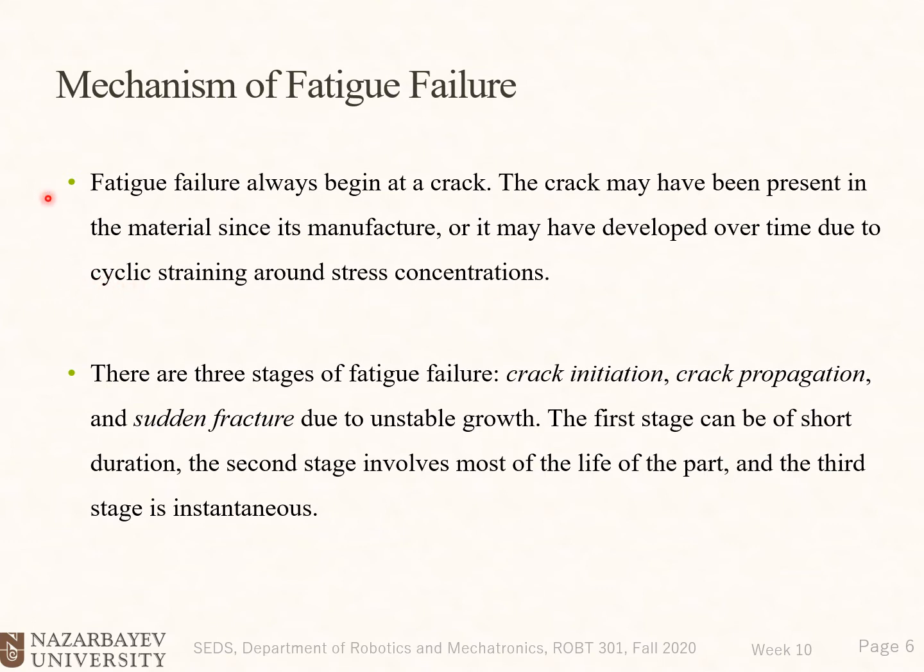So since it goes under stress cycles, and the stress becomes positive and then negative, there will be a stress cycle, and when there is a crack in the part, tips of the crack usually create a stress concentration, enhance the stress, and the crack basically develops and progresses forward, and the opening of the crack becomes bigger